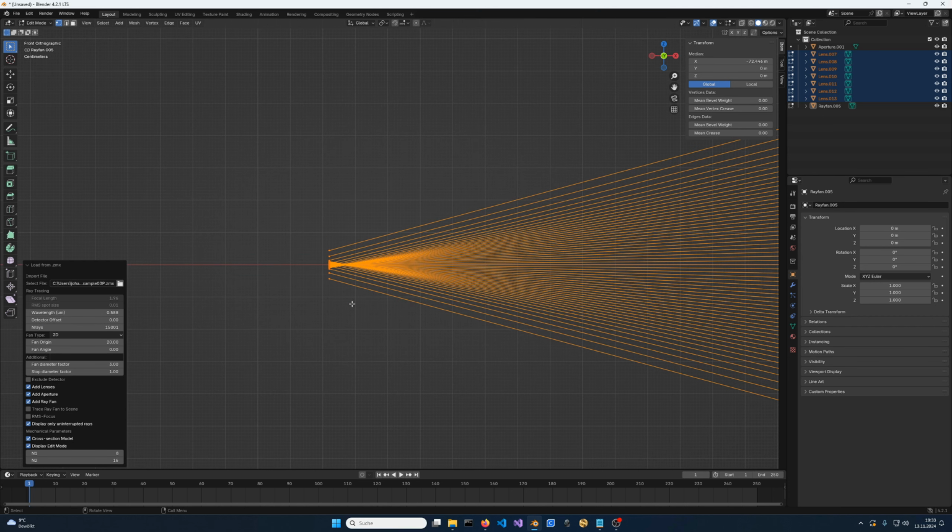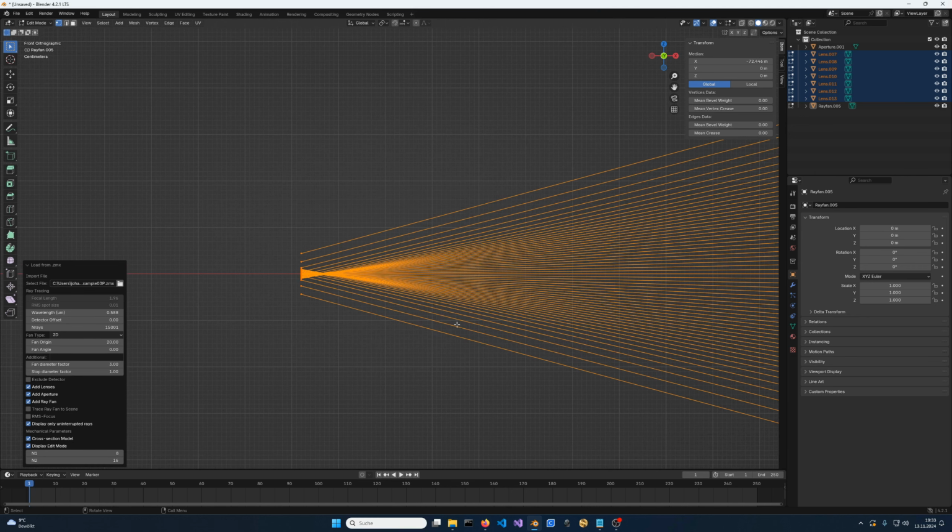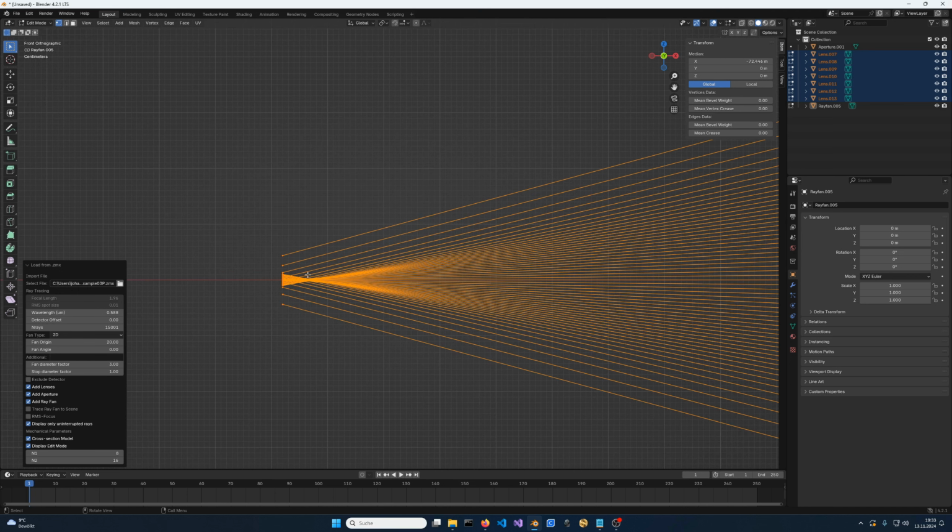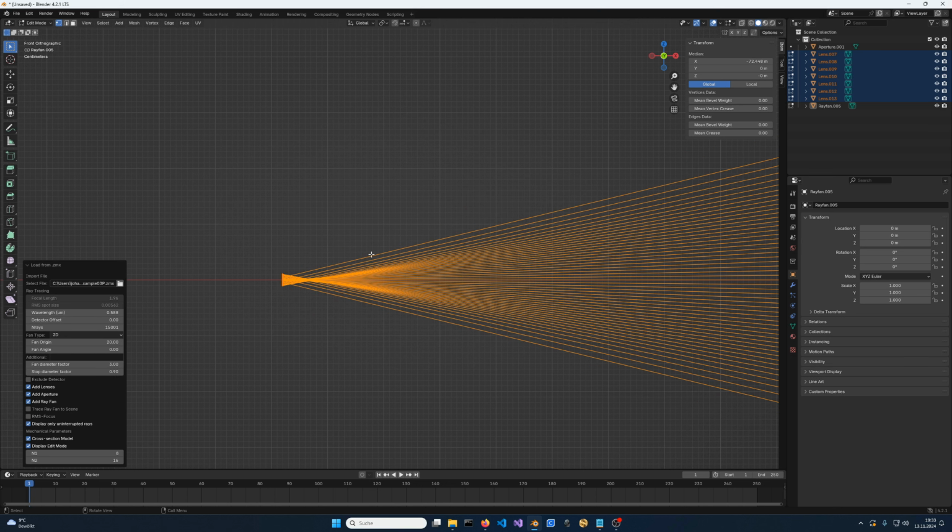What we do see here in this 2D view is that the outer rays of the ray fan have some residual aberrations relative to the inner rays. So it looks like there would be a pretty good focus spot here if we discarded a few rays on the outside. And indeed, if I stop down the lens by 10%, still a few aberrated rays. 0.8, now it looks like there is a rather clean focus generated, whatever that means, and the RMS focus would indeed place it there.